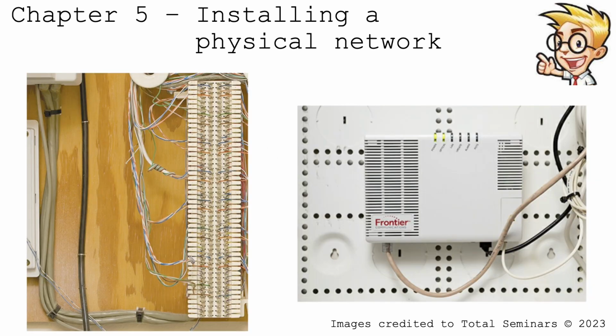Okay. Earlier I was talking about 25 pair and 100 pair cables. Here's an example of a 25 pair cable punched down onto a legacy 66 block. So you'll find those in different telecom rooms like that.